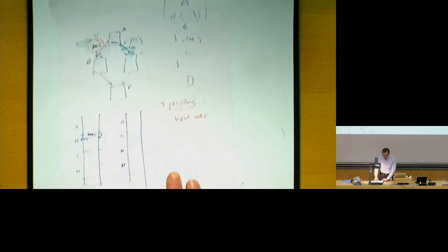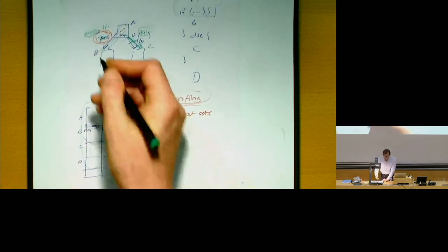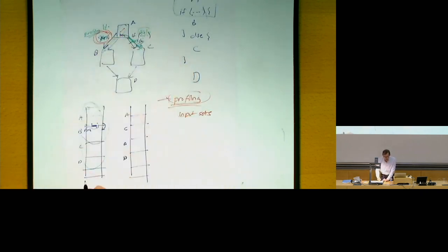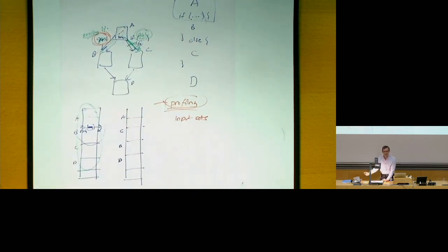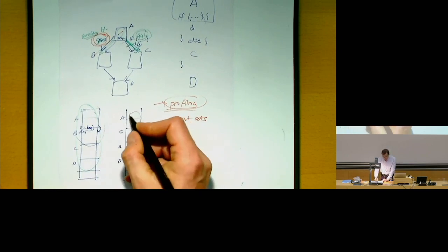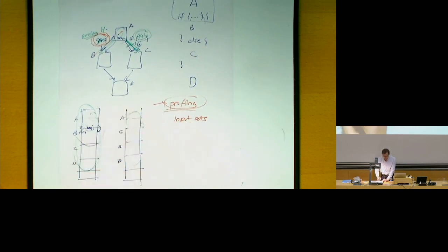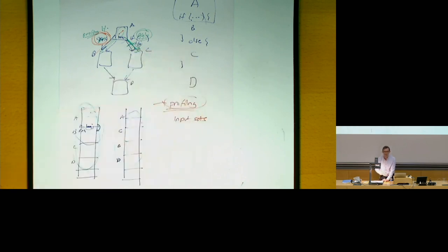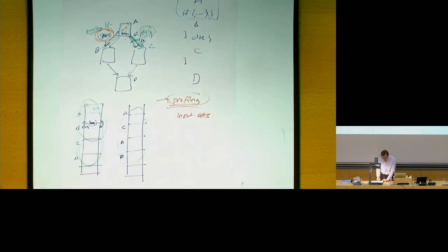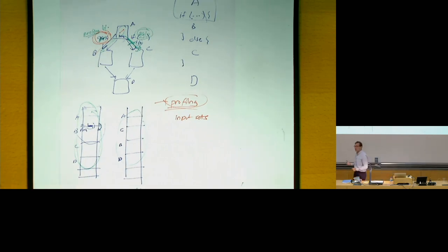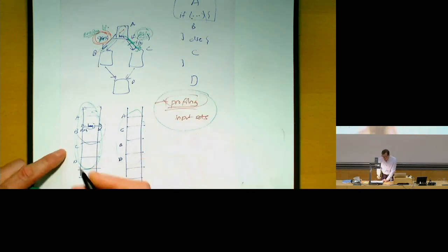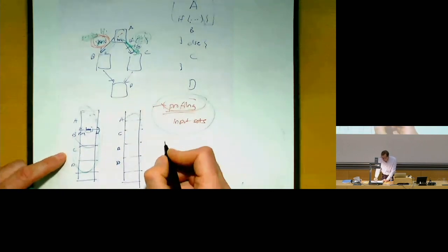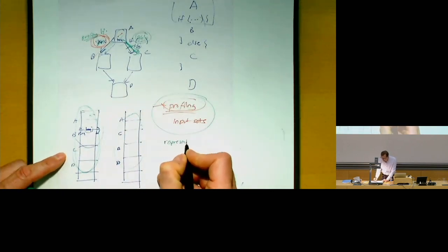So the compiler laid out the code this way, assuming that hopefully the branch will go this way 99% of the time. But in real life, the branch goes the other way 99% of the time. So you really needed this one, but the compiler gave you this one. So the prediction accuracy now becomes 1%, assuming you have a prediction that says next PC equals PC plus 4. So this shows you the importance of a compiler, right? But this is tough, this is not easy. Profiling is always subject to the representativeness of the input set.